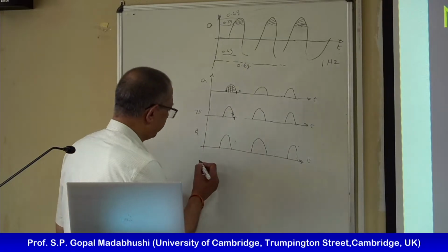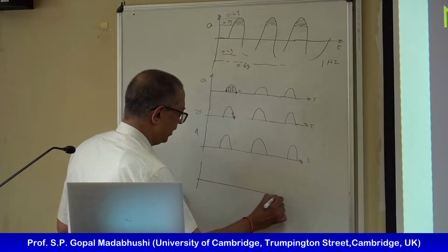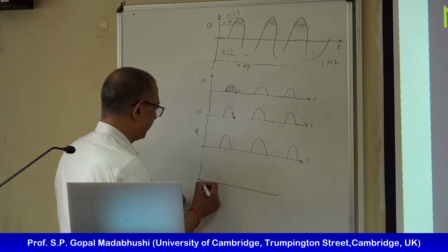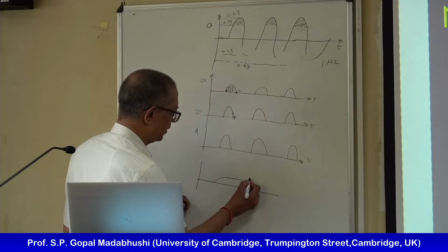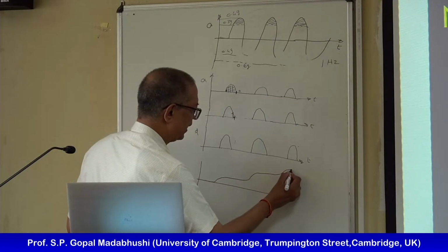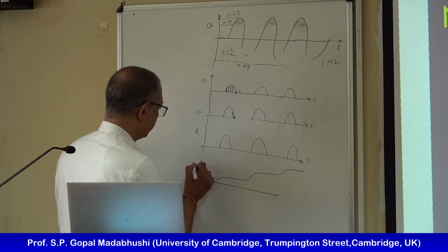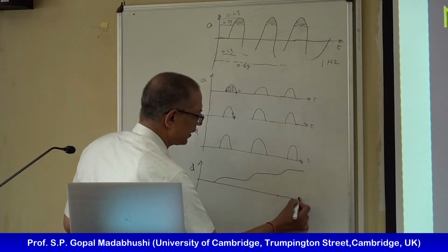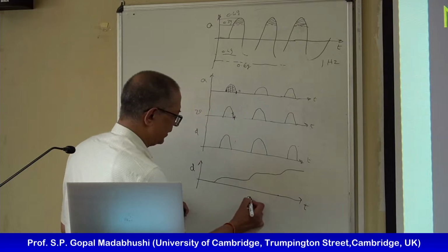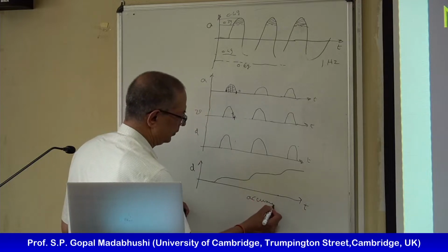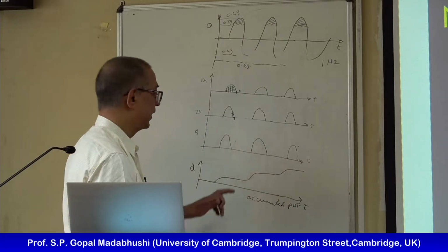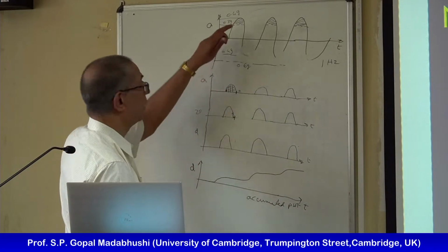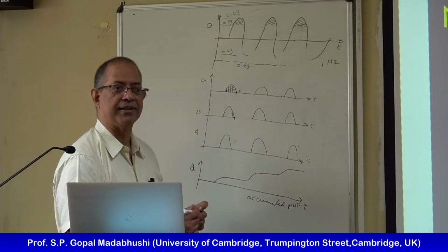If I look at how this will accrue with time, it looks like that. This will be the accumulated displacement versus time plot. Does it make sense? So it will accrue displacements whenever it crosses the threshold acceleration.